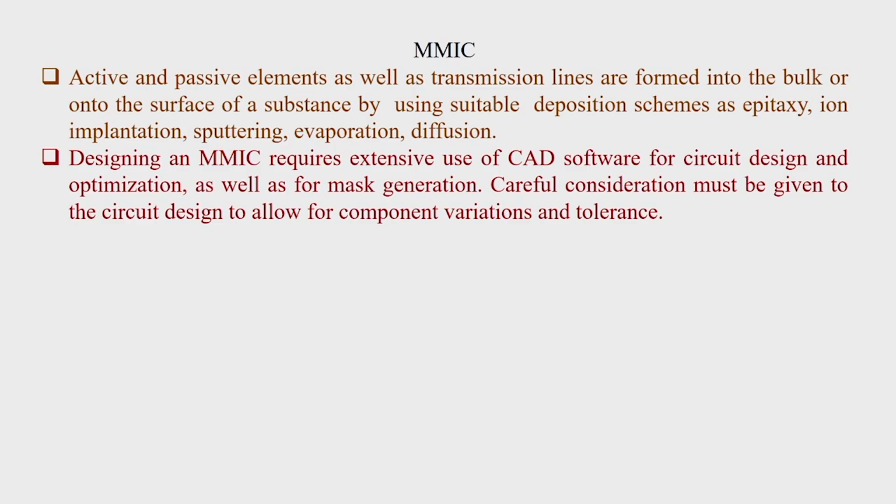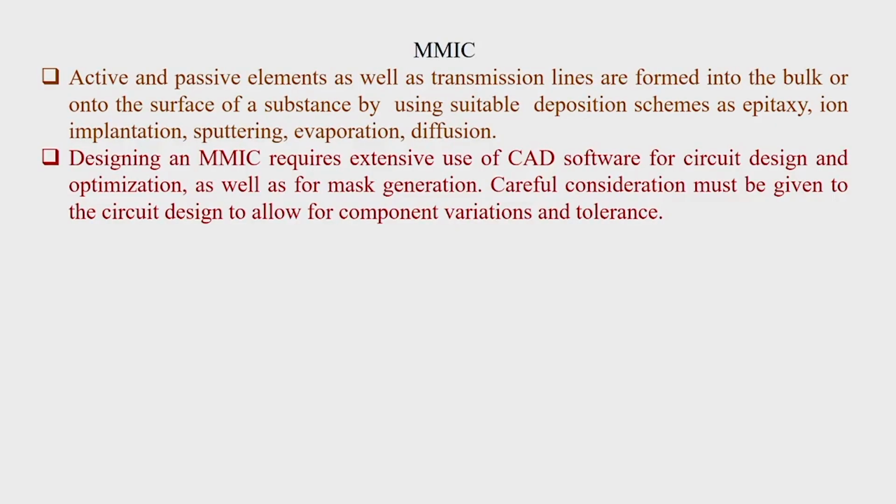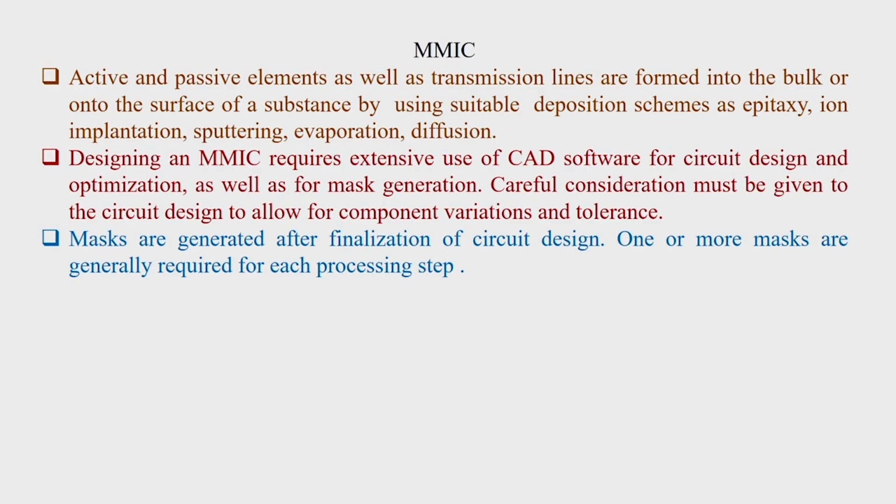Now, MMIC involves several sub processes and several levels of maskings are required. Careful consideration must be given to circuit design to allow component variations and tolerance. Masks are generated after finalization of circuit design. One or more masks are generally required for each processing step.